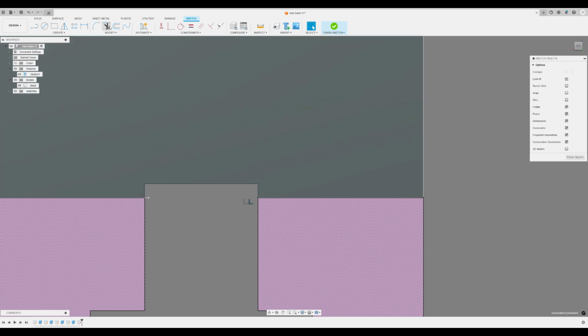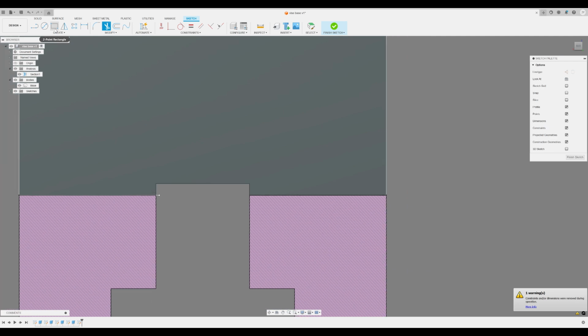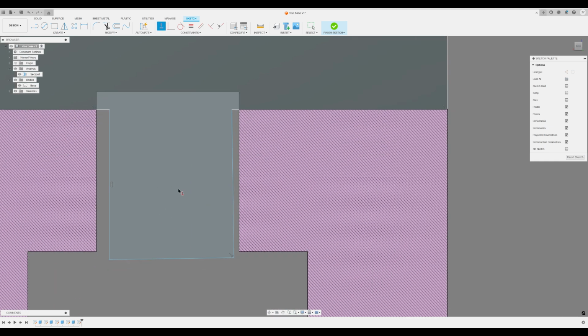This one line right here, I'm going to take the snipping tool and cut that off because I don't actually want it to end right at the corner. I'm going to let it be parallel. See how it kind of snaps to parallel? Right there, but we're going to come down, square, up. Obviously this line isn't square, so we can come to our constraints, horizontal, vertical. Hit the constraint on that, it's square again.